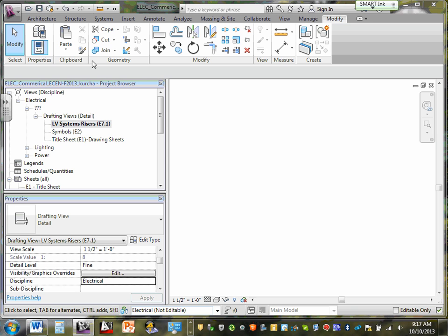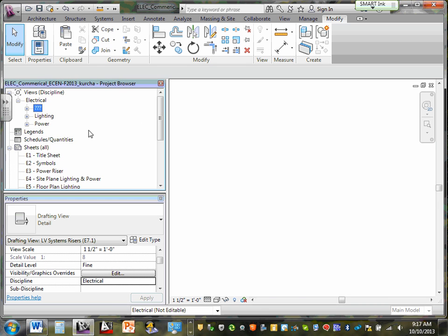Let me show you. So later on, here's all my stuff ready. Here's my schedules. Can you guys see where schedules are? When you run a schedule, in order for the schedules to show up, two things must happen. You must drop a panel, otherwise it won't show up. Then, three things actually. One, you must drop a panel. Then, you must circuit to the panel.